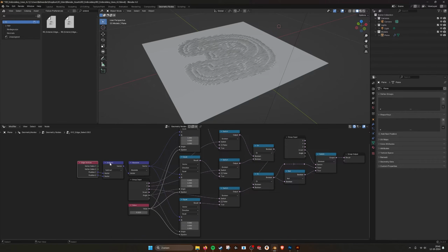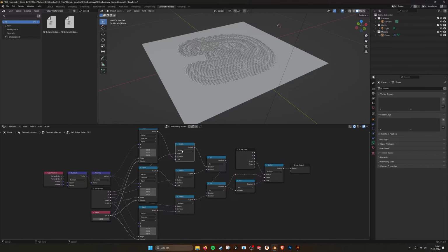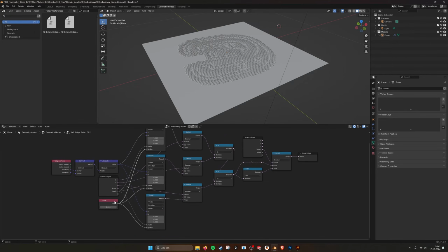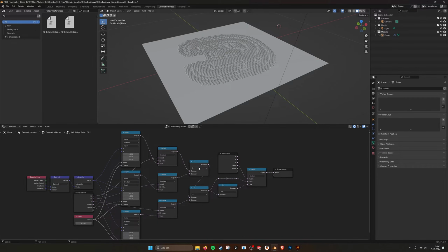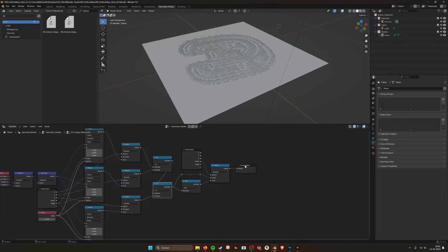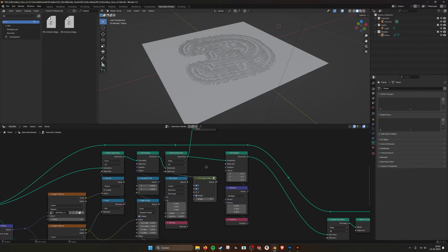So I take the position 1 and 2 of the edge vertices and then subtract them. I use the absolute, and then I program a switch, and I use an Equal. Here you see it's the X, the Y, and the Z. So you can choose, you have the epsilon of 0.1. You can choose which one to tick, and it sends them through the switch. And here by the OR node of the Boolean, I combine them into the output. And that's how it works for the XYZ edge selection.